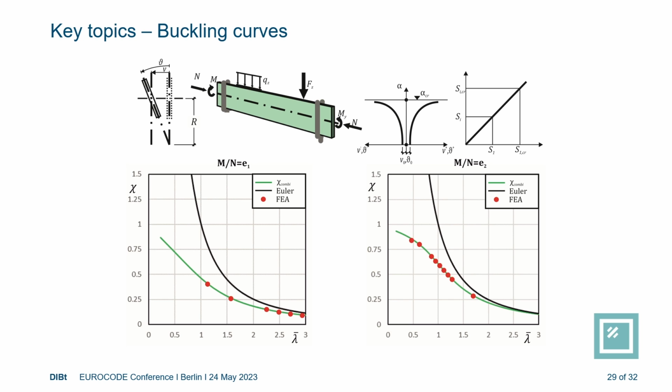You can see this is the analytical approach, and this is the finite element analysis results. So it is a little bit easier in glass because it's perfectly elastic, and we don't have so many different shapes. It's always rectangular, only that it is laminated or mono. These are the simplifications compared to other materials in this respect.